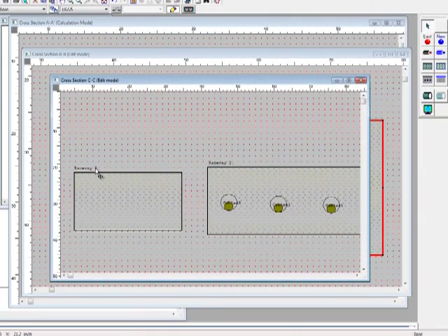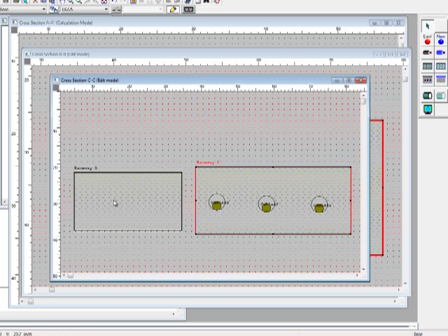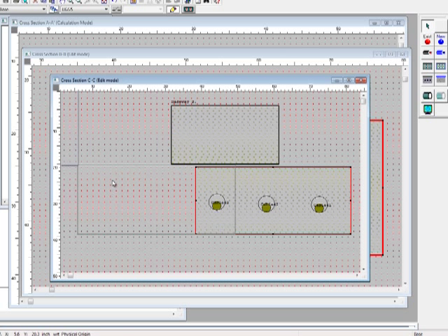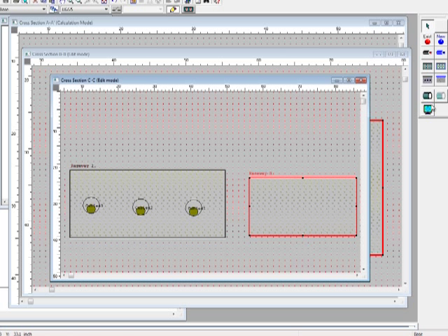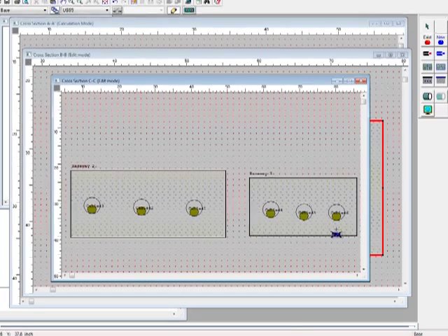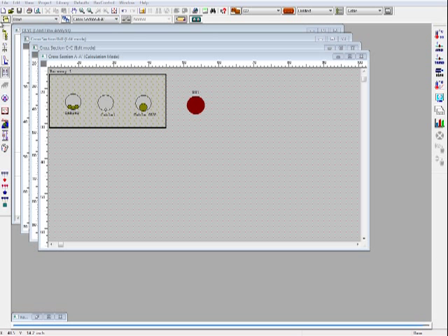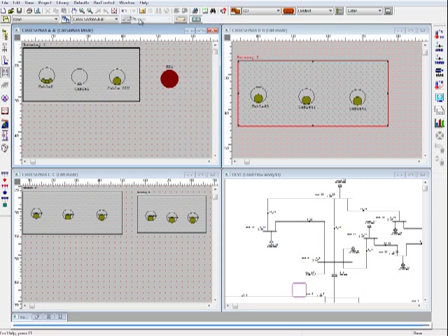So this is raceway 3 and this is raceway 2. You can relocate it like this, and you can drop the conduit here. By double click you can add multiple conduits, or double click on the cable to drop multiple cables on the system. You can simply go to the window menu and do the tile, and you can see all the cross sections AA, BB and CC with all the details of the duct banks to represent the entire composite underground raceway system.